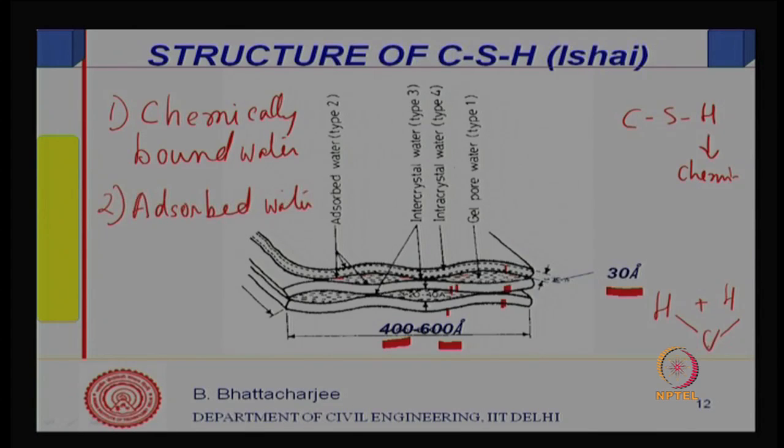And besides that, of course, you can have capillary water, which is taken up by suction, capillary suction, right. If you have larger size pores, or relatively some mesopores, not very small pores, fine particles, of course an adsorbed layer would be there, but in slightly larger size pores, water can penetrate by capillary suction. So, the third type of water held is capillary water,